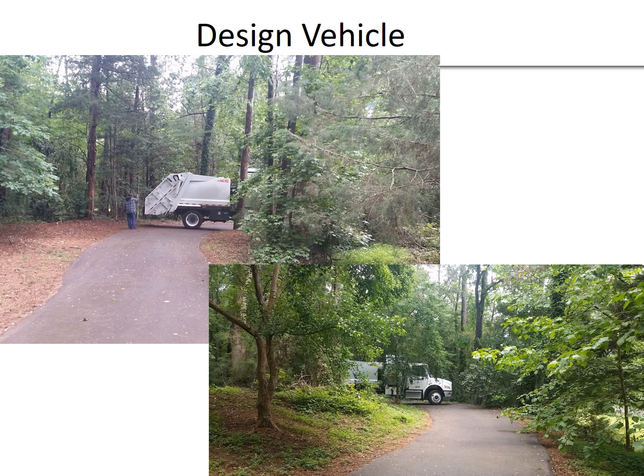It just brought up a good point about what is the largest common vehicle we expect on the highway you're designing in the design year. So it isn't a once in a lifetime type of event, but what is that largest common vehicle that you're designing for? A lot of the highway dimensions are going to be based on that design vehicle, particularly at intersections.